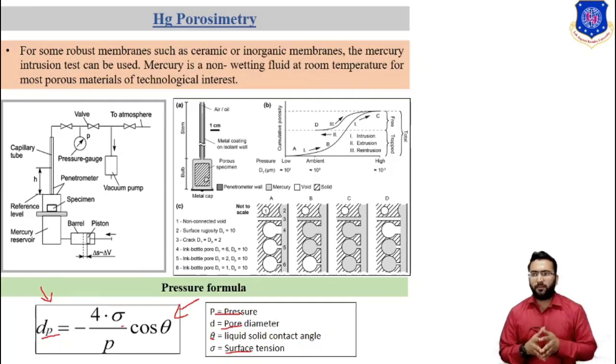applied to a porous sample immersed in a mercury bath, and monitoring the increase in volume of mercury intruded for each new applied pressure. The pore size distribution of the sample can be estimated in terms of the volume of pores intruded for a given diameter. Of course, the above equation, relating the intrusion pressure P and pore diameter D, assumes the pores have a circular cross section.